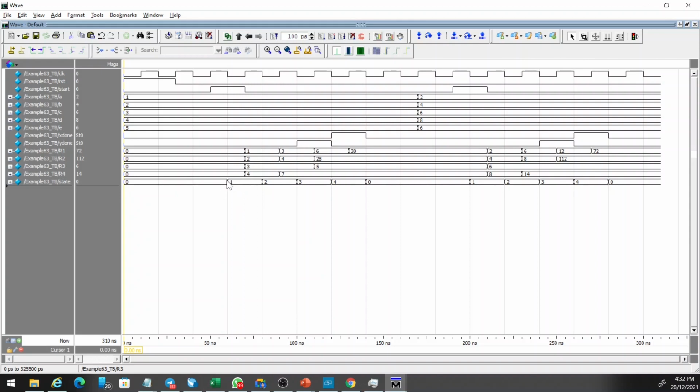If you load the data in practice at the beginning of this, you might sometimes miss the value, because in order for the register to be stable, there is what we call the settling time, right? So before the data can be loaded into the register, we want to make sure that everything is okay first.